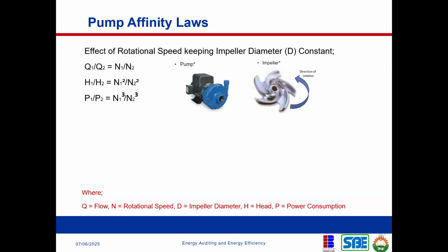When I say fluid, it can be water, it can be diesel, it can be anything, right? So affinity laws help us understand that relationship. In this case, Q stands for the flow of the fluid. N stands for the rotational speed of the impeller. D stands for the impeller diameter. H stands for the height in terms of meters. And P means the power consumption, right?